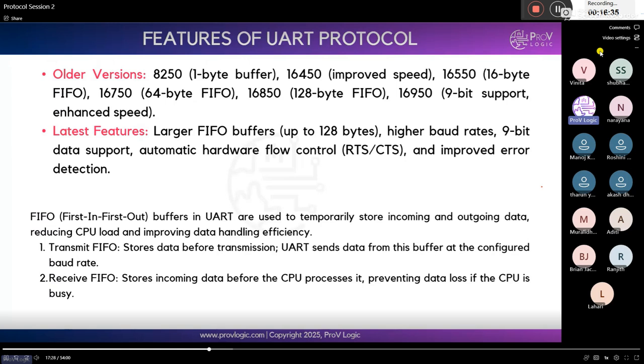And coming to the disadvantages, there will be a lot. It works at a limited speed, and baud rate mismatches. Mostly, we will get baud rate mismatch issues between transmitter and receiver because it's not a fixed clock, right? We are just putting some value as the baud rate, in the sense it's just a value at which the data will be transferred. So we will get a lot of mismatches between receiver and transmitter.